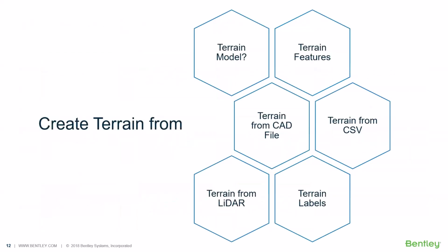Going ahead, there are certain formats that we can use to create terrain from. There are different options that we can choose. I have brought in this element so you can understand that the terrain, or the surface mesh that we are going to create, can come from older file formats like an XYZ file, a text file, a CSV file, or something most people use right now, a DWG drawing file from your surveyor, having all your survey points and lines with different levels.